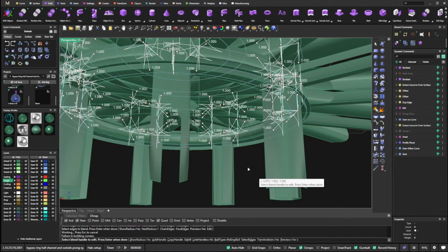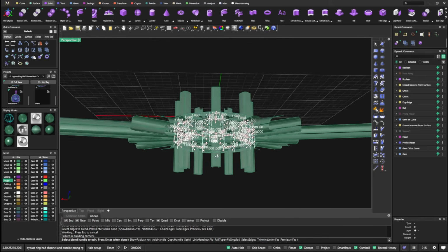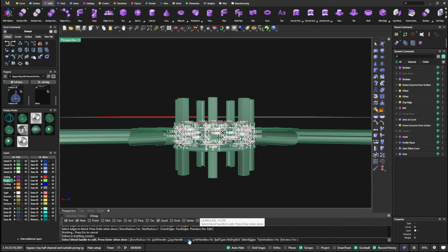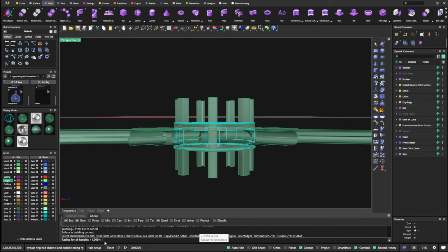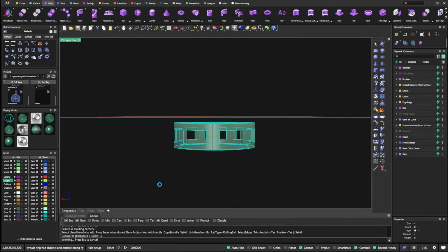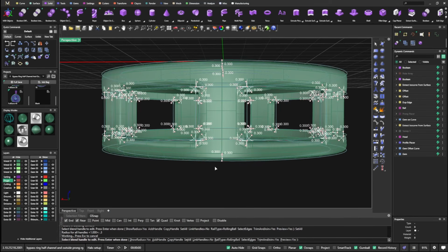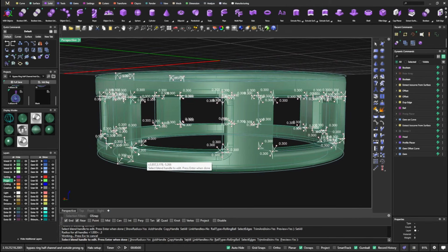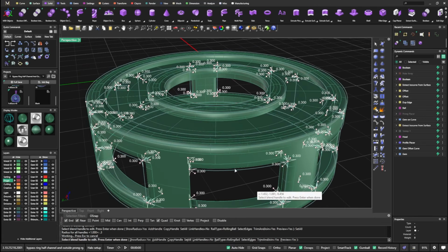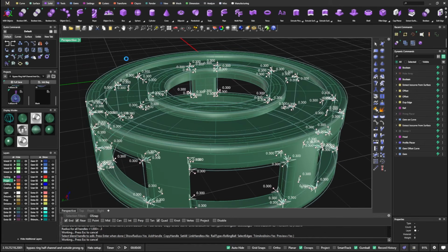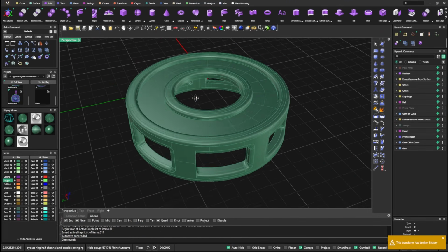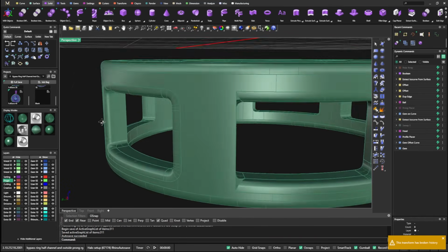And of course it's going to blow, which it does, right? No big deal. I'm just going to go down here to set all, click on there, and then I'm going to say I wanted, let's try a 0.3 and hit enter, and then wait for that. And there, it looks like it came out okay, and we have all those areas filleted, and I'll just go ahead and right click to accept all those fillets. Now you can see we have a much softer look, right?